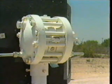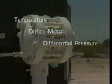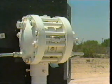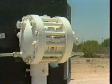For instance, to determine the volume of NGLs with an orifice meter, the temperature, differential pressure, and static pressure, or static constant, must be known. The orifice meter station creates a differential pressure and records the differential pressure and sometimes the static pressure. For a more detailed discussion on orifice meter stations, review the tape on orifice meter station fundamentals.